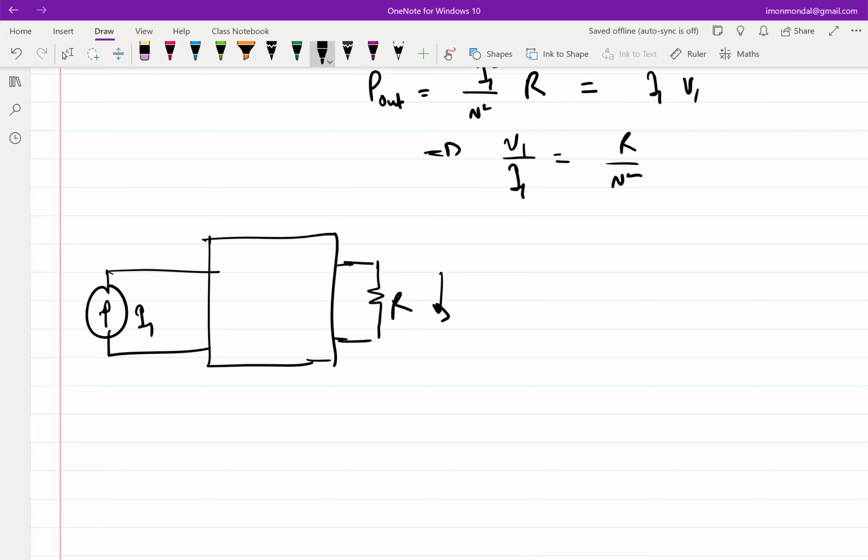A capacitor in parallel, right? So anything in parallel will reduce the current through R. I mean, that's trivial. I can put a capacitor, I can even put an inductor. Right? So let's stick to a capacitor. So I put a capacitor here. So what will be the fraction of current going into R?